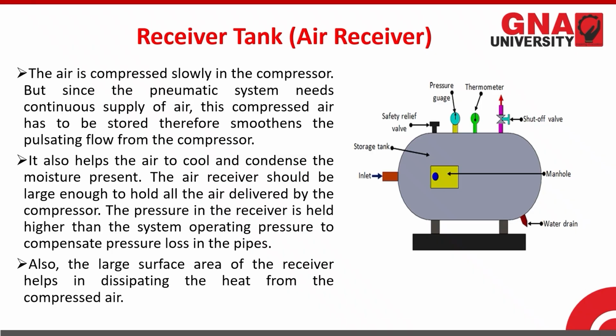It also helps us to cool the compressed air. As we know, after the compression stage, the temperature of the air goes up. So we cannot use that air directly in our pneumatic systems because it may damage the plastic components. When it is stored in these receiver tanks, due to the large surface area of the tanks, there will be heat transfer, and the air inside the receiver tank will get cooled.